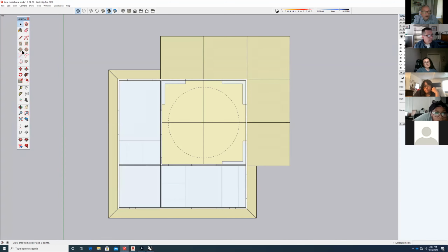And I am going to draw a circle. Now watch me do this, and then you do it yourself. And I have a brief explanation here about SketchUp. Even though you can do curves in SketchUp, they look like curves, circles, and arcs, and all kinds of goofy shapes. In fact, they're made up of segments of lines. There is no such thing as an absolutely true curve in SketchUp. They're imitations. There are a bunch of lines.